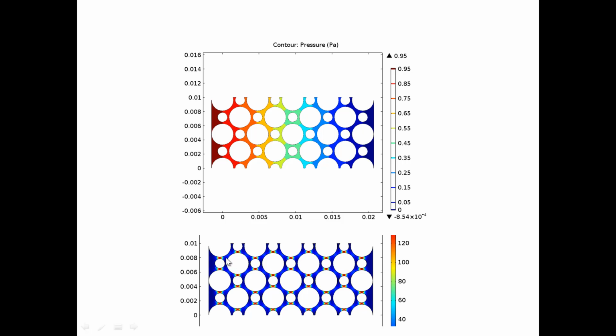So we have very small pressure gradient throughout much of the pore structure, and the pressure drop that we would see over this entire experiment was really a result of pressure drops that occur over several localized areas. So that's somewhat of a different view than we get when we use the homogenized view of a porous medium.